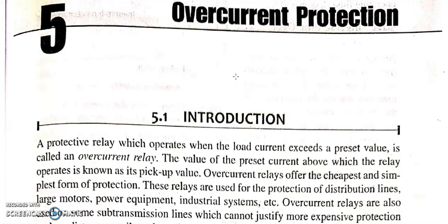At present we know that electromechanical relays are widely used for overcurrent protection. We also discussed that the induction type construction is commonly used. With the development of numerical relays based on microprocessors as well as microcontrollers, there is a growing trend to use numerical overcurrent relays compared to traditional electromechanical relays. As we discussed in an earlier class, numerical relays have advantages over electromechanical relays, so they are gaining wider attraction.